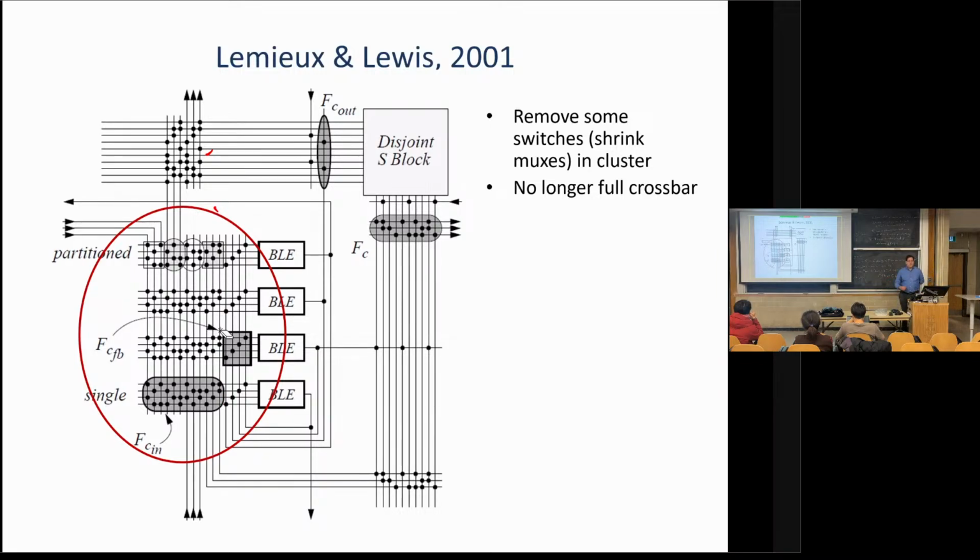So if I count up how many dots are in any one of these horizontal lines, that says how big a mux I need. Right? So it's like a 4 LUT. I count those dots, and I need 1, 2, 3, 4, 5, 6, like 7 to 1 mux. Okay? And if I counted all the wires, it looks like it's about 14 wires.